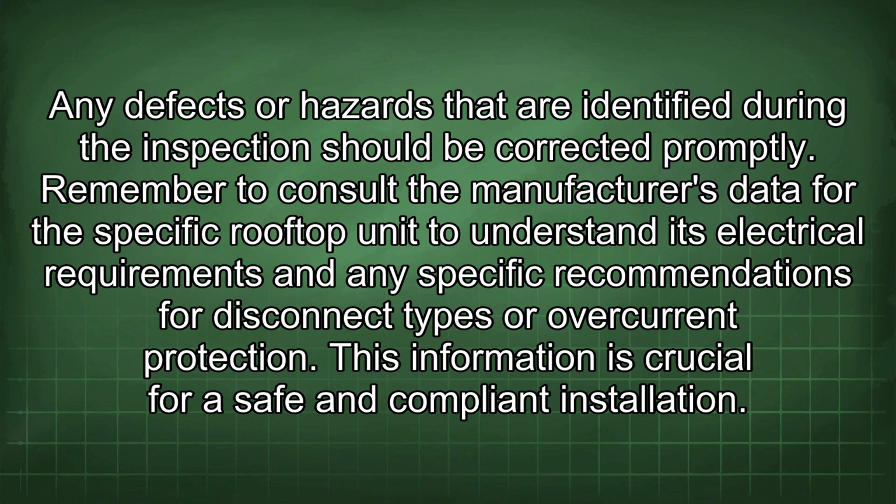Remember to consult the manufacturer's data for the specific rooftop unit to understand its electrical requirements and any specific recommendations for disconnect types or overcurrent protection. This information is crucial for a safe and compliant installation.